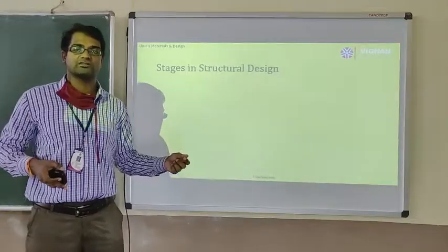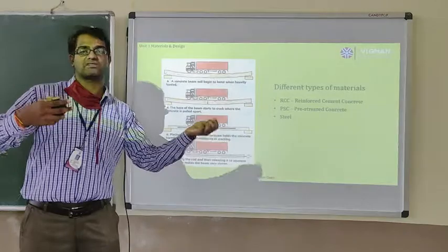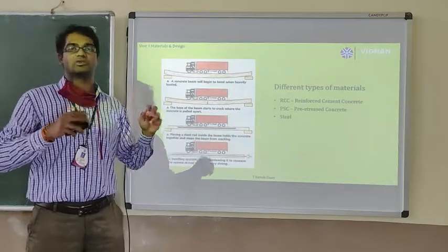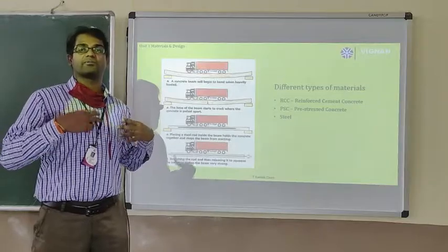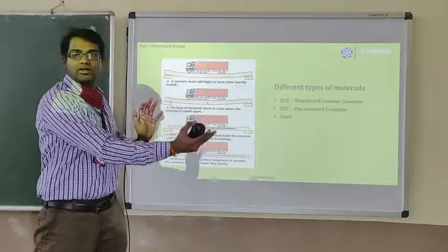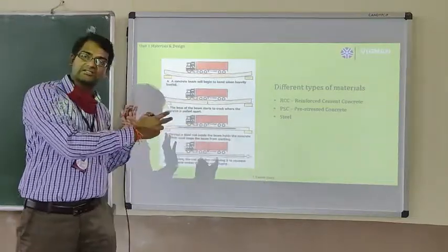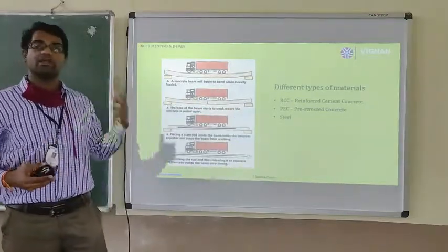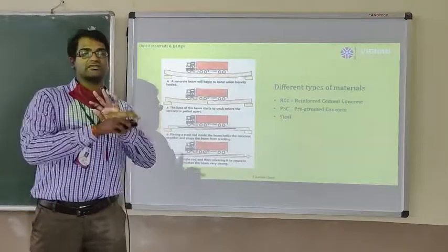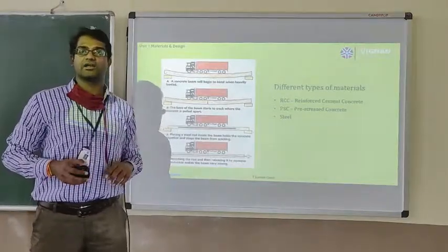This stretching will induce stresses before it is loaded. That is why we call it a pre-stressed concrete structure. In pre-stressed concrete, the cement concrete is pre-stressed before loading it, so that your vehicle can travel smoothly. This you will learn in PSC, which is a completely different subject.